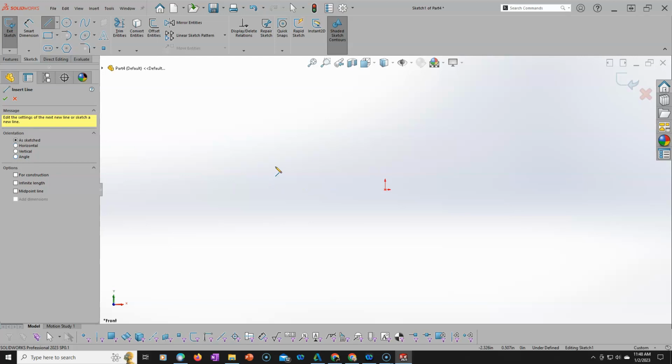All right, visual clues on the work area. So as I'm dragging around, I have inference lines. Those little blue dash dotted lines are telling me that I'm vertical too. The little white box with the vertical line is also saying that you can infer, but it's not going to automatically apply.